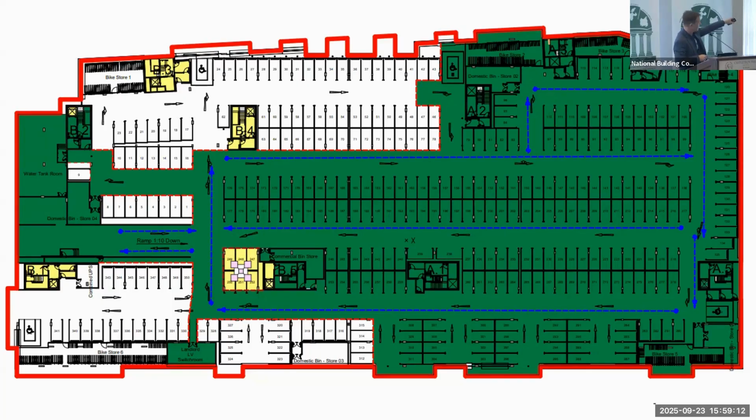And if you're including them, then you need to access them and you need to escape from them, which then means you need to look at your escape routes as well from there. And if that's the case, then you're probably looking at alternative escape routes and not just your first phase building. Takes a lot of time to even get to that point, right? Just to consider all the mechanical and electrical considerations, all your fire considerations, fire signage considerations, and all that needs to be done and completed and presented to building control for discussion.